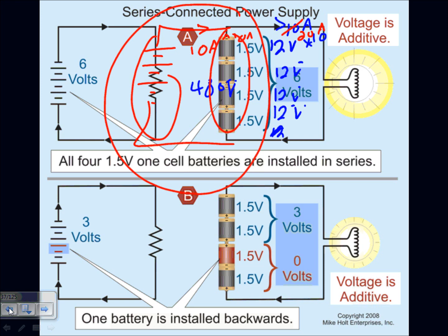The worst thing that could happen to you, though, is to take synchronous generators and do that to the synchronous generators. Put them in series. Oops. You wouldn't get a whole lot. This is for the DC concept. In generators, we put them in parallel. You hear at work, they say, we're paralleling three generators, 2 meg each. Synchronous generators, we put them in parallel.